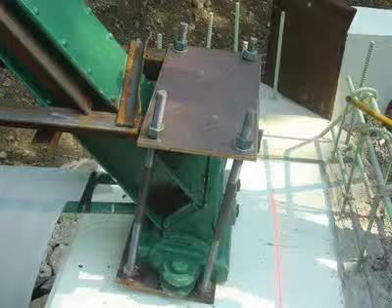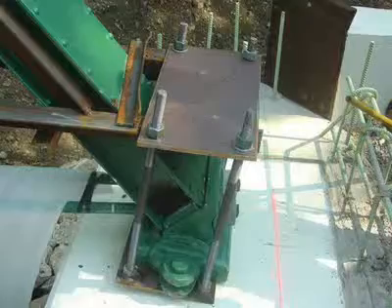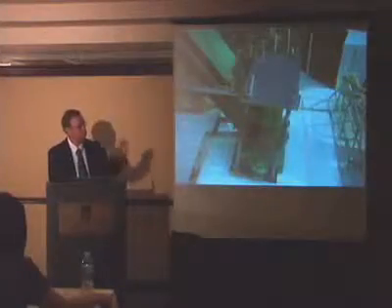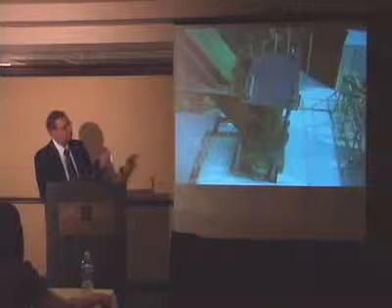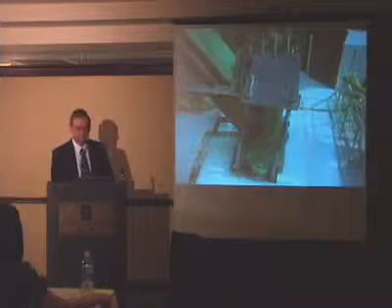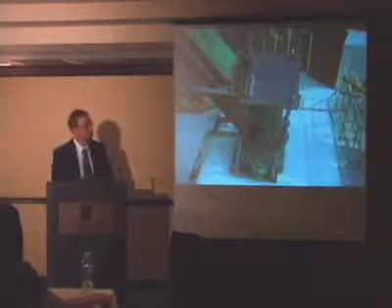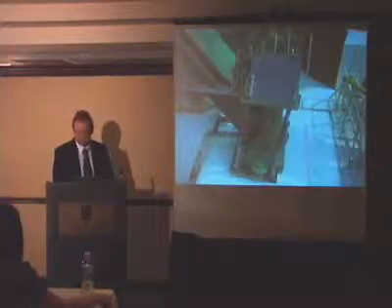The bridge, the way it was originally manufactured on falsework, was such that if we simply lifted it without any stiffening, we would have lost it. Some of the sections would have fallen apart. So we had to add a few temporary bracing, just to keep the bridge together.